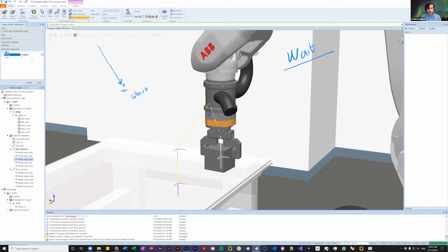But if you disable in position, it actually starts counting from somewhere here before getting to the target. And it is not a good idea because, for example, imagine that you want to close the gripper once you get to this glass.